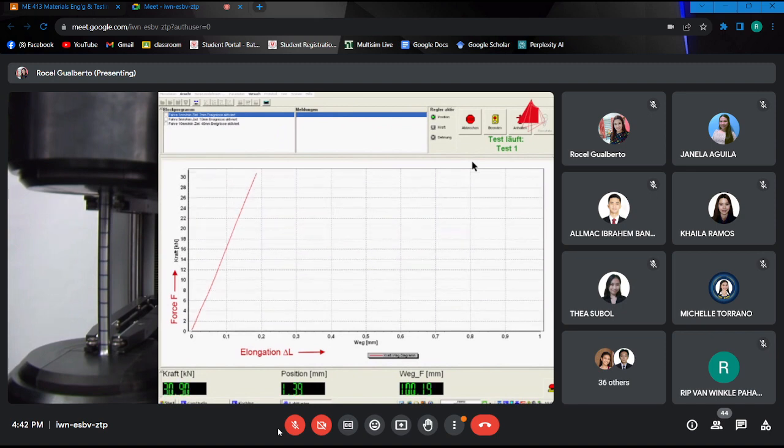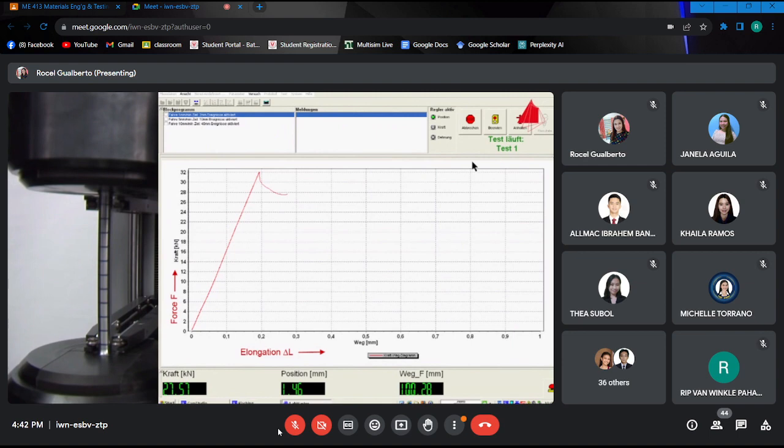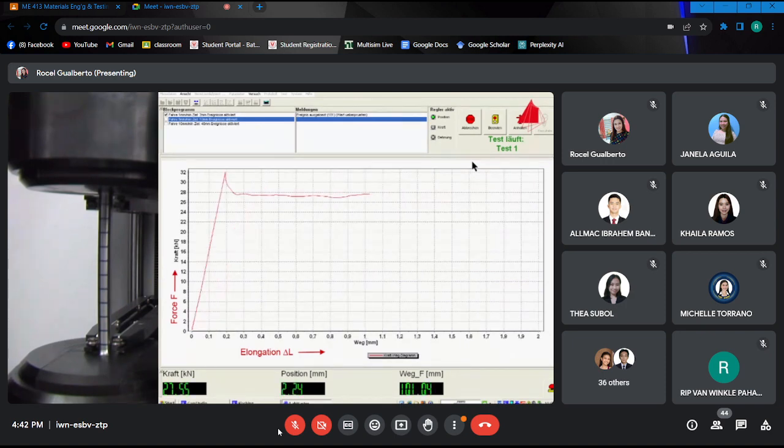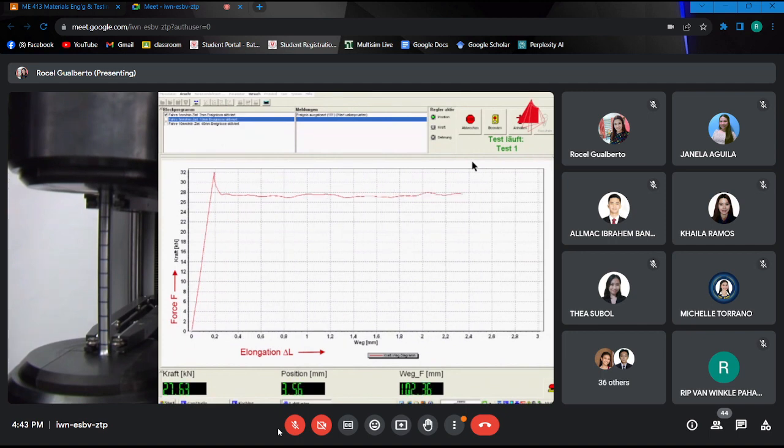The plastic deformation starts abruptly and is accompanied by a sudden drop of force. If the test piece were to be unloaded now, it would not spring back to the original length, but instead show a permanent elongation. In the next stage of the tensile test, an almost constant force level with slight fluctuations occurs. This phenomenon is called the Luders effect.